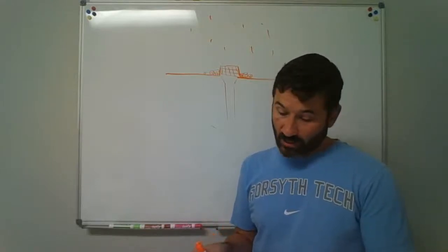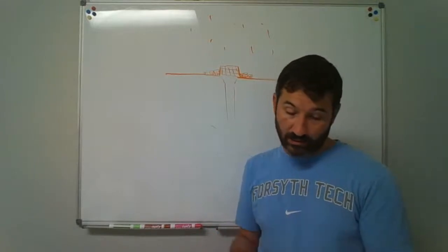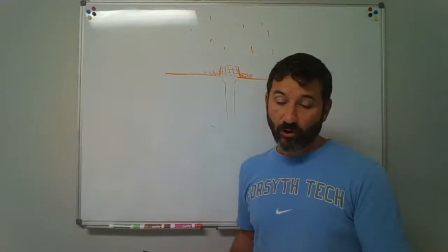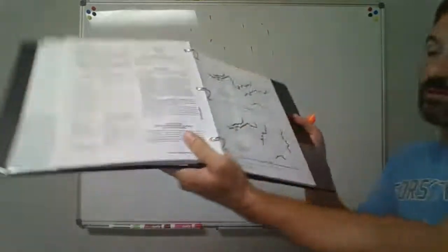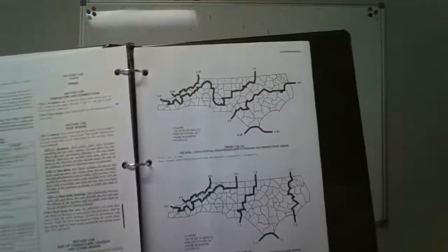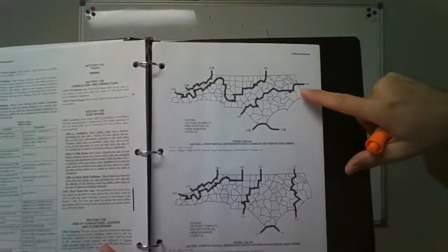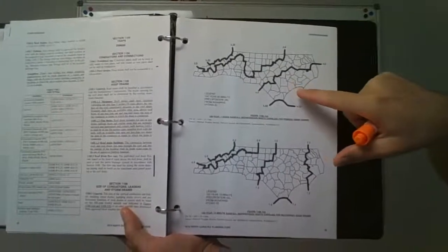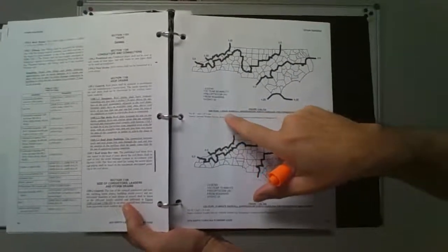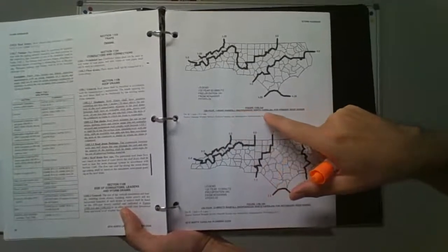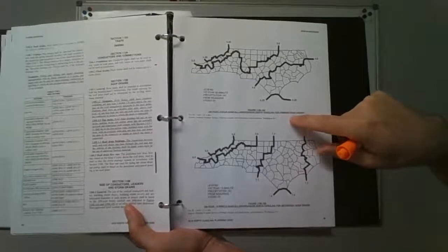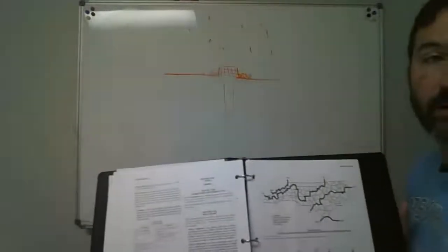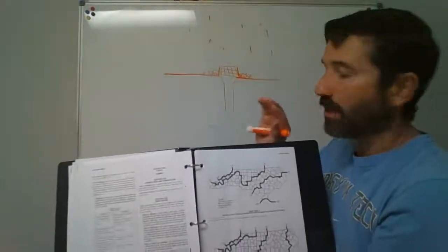Okay. Now if you go look at page 89, what you have here is some rainfall rates. If you don't have your book in front of you, this is what the chart is going to look like. You have this top chart, and you'll notice that's the state of North Carolina. We've got 100-year, 1 hour rainfall in inches per hour for North Carolina for primary roof drains. Now they're going to give this for the primary roof drain, which is the primary drain that services the roof.